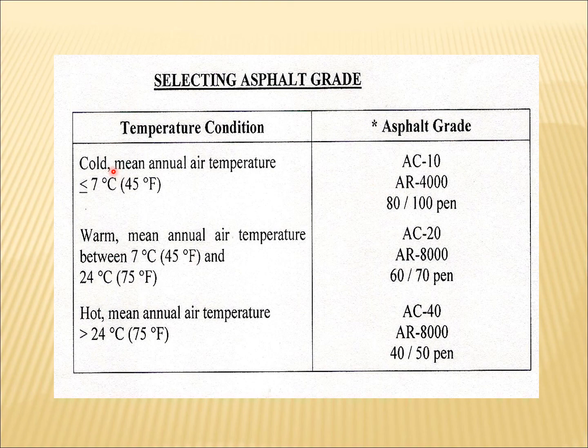For cold condition, AC 10, AR 4000 and 80 to 100 penetration grade of bitumen. And for warm, AC 20, AR 8000 and 60 to 70 penetration grade bitumen.